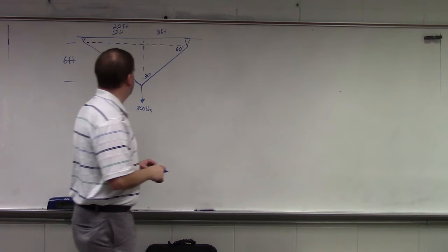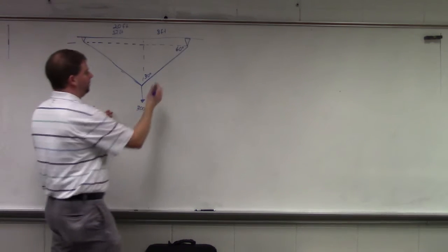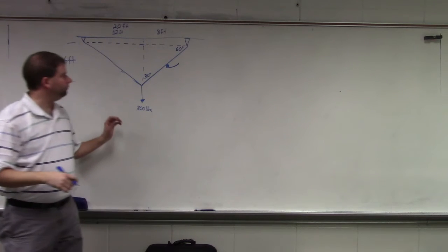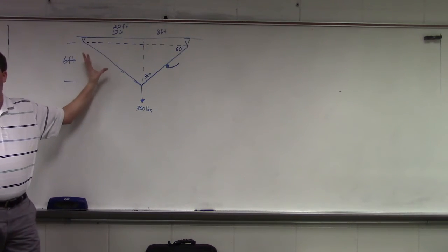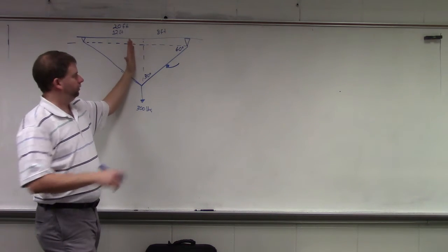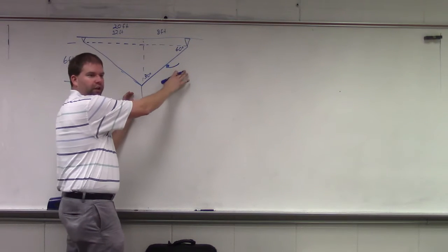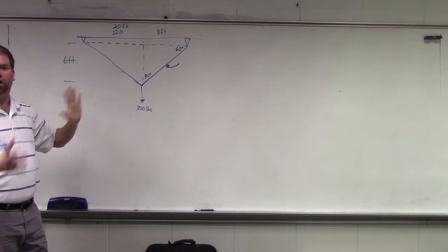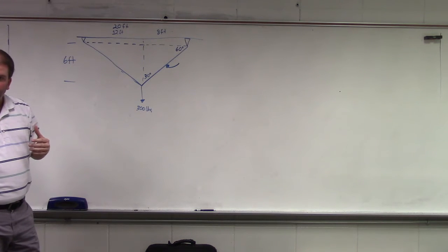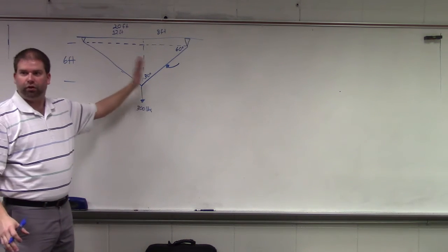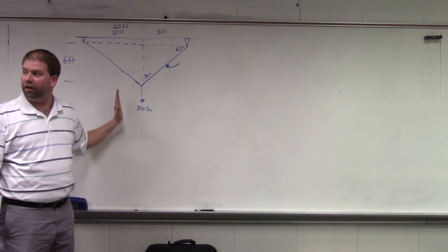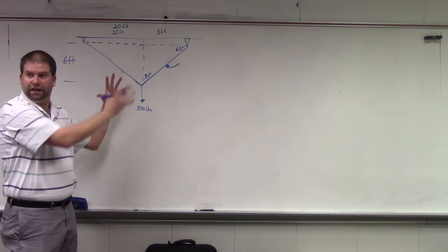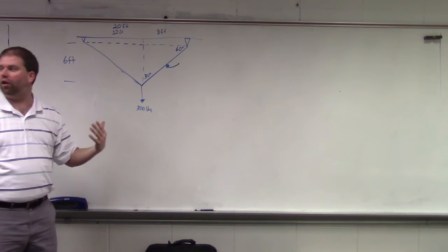Okay, so, well, that's okay. For the sake of this problem, we're being asked to solve this, correct? Yes. The other side doesn't matter. Okay, so let's suspend the disbelief of what's actually going on in the picture, and we'll use the angle that you have here and draw this member to complete your force polygon with the line of action that you need to close the polygon, okay? If we think back to what we talked about with force polygons in general, if we were to draw it with the actual lines of action that it has, and we don't close that polygon, what does that tell us? Do we have static equilibrium? No. It has to be closed. We're gonna be rotating this thing somehow, okay? So in the field, how do we resolve that if we don't have it?